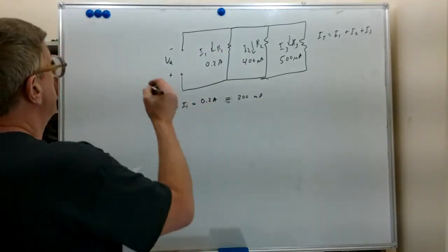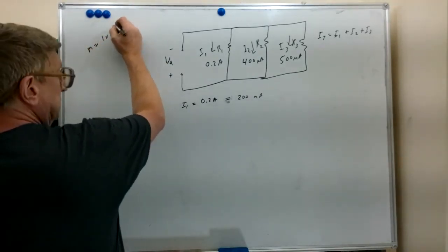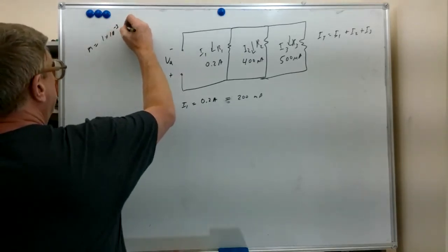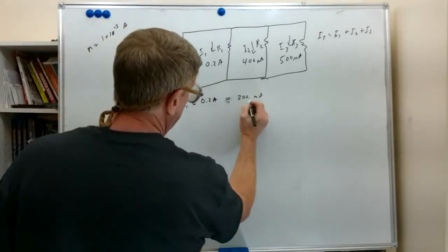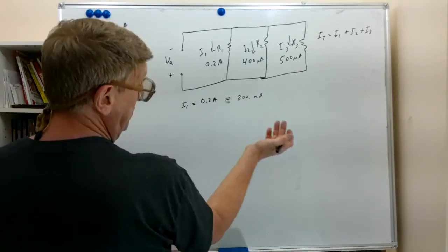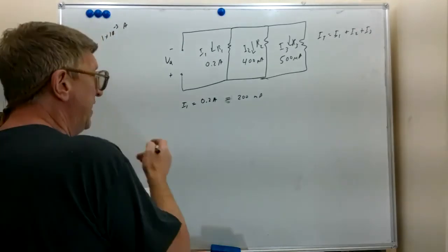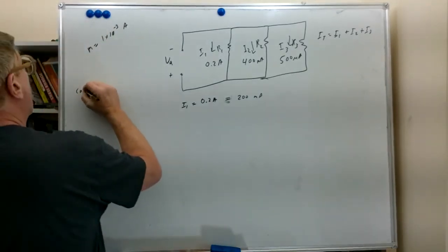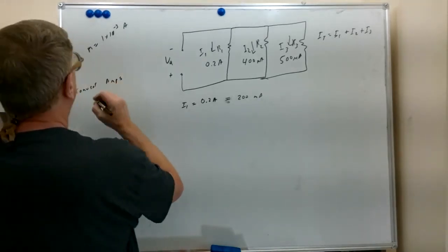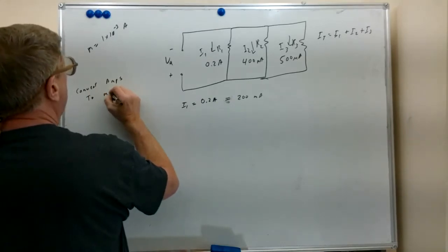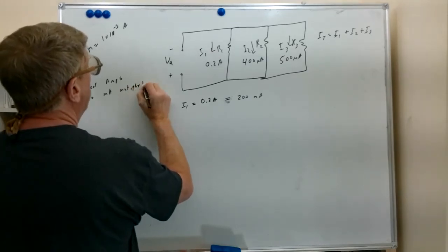And you remember that a milliamp equals 1 times 10 to the minus third amps. So if we have this in milliamps, the decimal point would be here, but the minus 3 would say, move it like there to convert it to amps, so it would be 0.2 amps. Another way to look at it, if you want to convert amps to milliamps, multiply by 1,000.